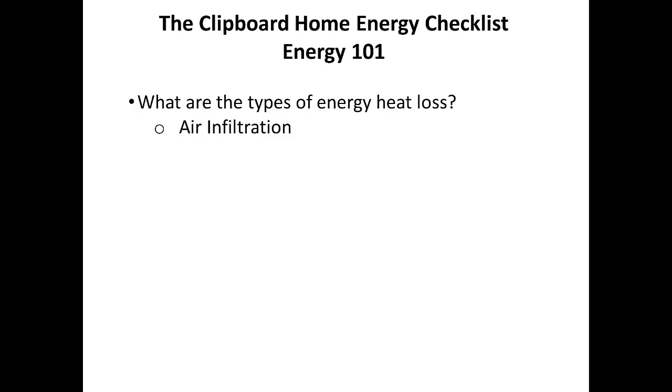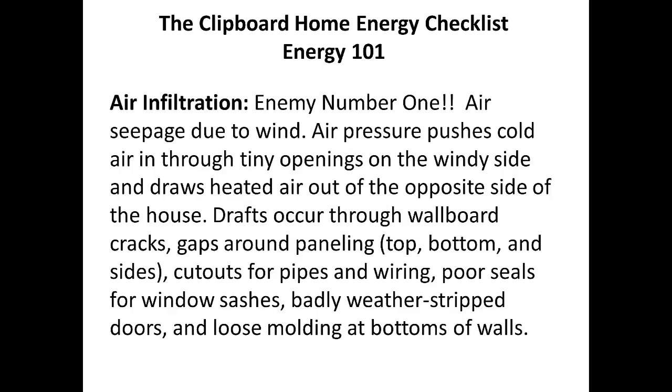And the first type of heat loss that we want to talk about is air infiltration. And air infiltration is enemy number one. And if you've ever felt a draft in your home, that is air infiltration. It's the air that seeps into the cracks of your home. And those are the things that when a professional goes after and tries to make a home energy efficient, that's the area that is really a key focus of the professional and should be of the homeowner as well.